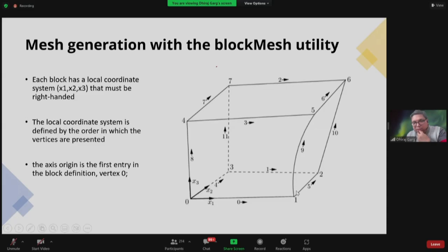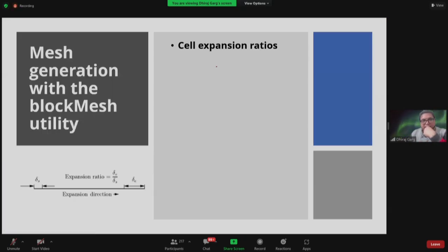You can give what should be the curvature of this line. And as I said, 3 points are always coplanar, but the 4th point may not be coplanar, and here that is the case. Because of this, these 4 points may not remain coplanar, and hence the center of the cell of this face may not be physically on this area, but its projection in this direction would be on the cell face. Okay, so this is how mesh is generated.